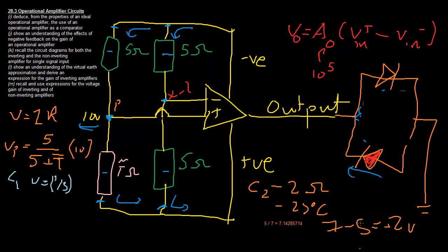So with a positive input like this, the output's also going to be positive. And what's the difference? Basically, that just defines the direction of the current to be opposite to what it was when the output was negative. So when we said that the negative one went from right to left, this positive one must therefore go from left to right, in this way. And if we send current this way, this diode no longer lights up, and this diode lights up, and it gives us a green light.